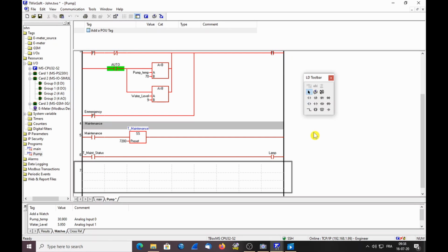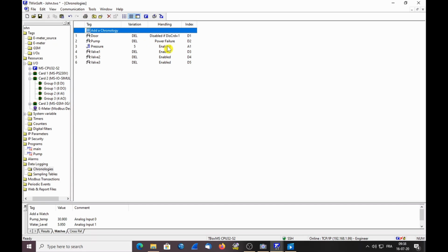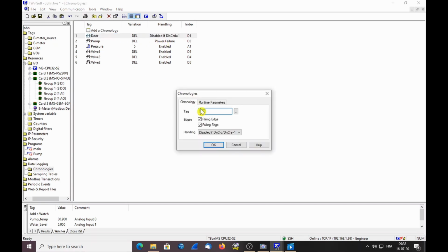Now I want, when the timer starts, to deactivate some features of T-Box. So the feature I want to deactivate is some recording in data logging and some alarm settings. Remember that when we define data loggings, we have an enabling, okay, here for instance. So the logging of the opening and closing of the door.